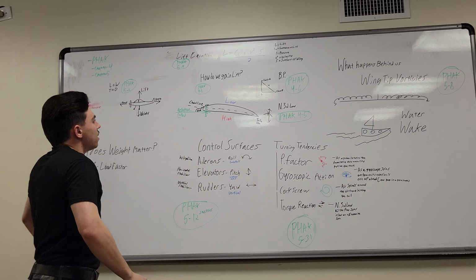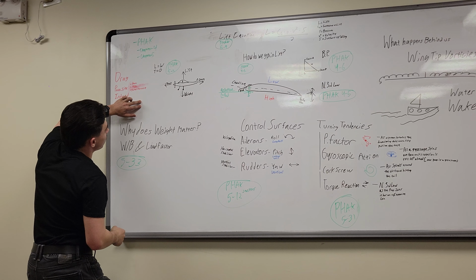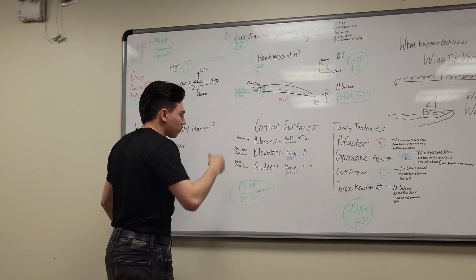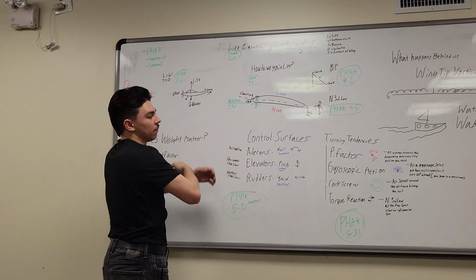So thrust, if we rotate this about 90 degrees and start rotating it, is similar to how we generate lift here. We're going to be generating lift forward, generating forward thrust, and pushing the wind behind us as we increase our RPMs, use our engine, use our prop. So looking at the aircraft, let's go over the control surfaces.